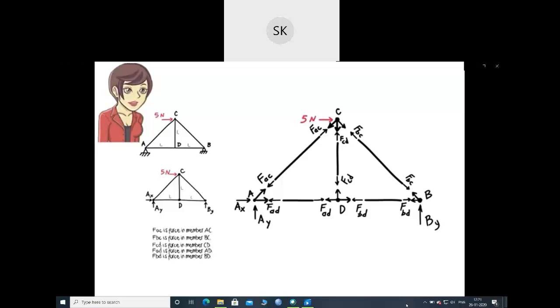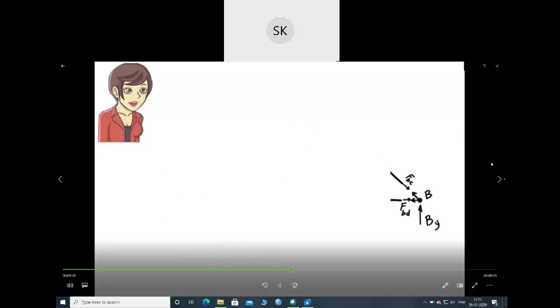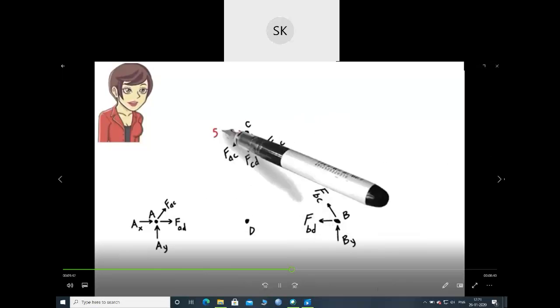The two force vectors shown in each segment cancel each other. That is, their sum equals 0. And since there is no bending moment or shear force acting on the free body diagram, the moment equilibrium equation is automatically satisfied. So now let's turn our attention to the joint segments.